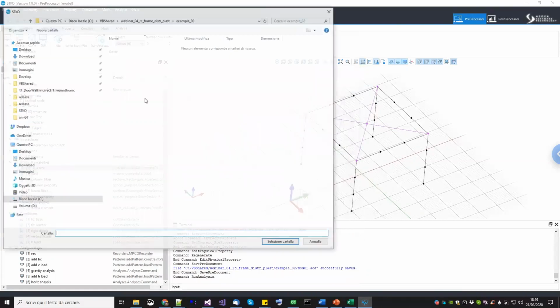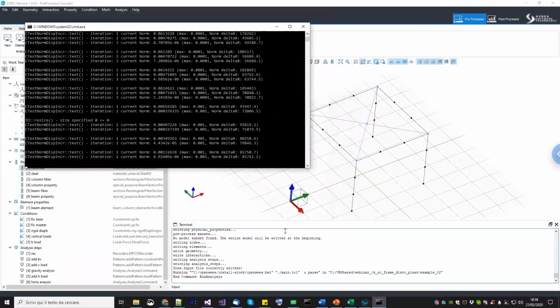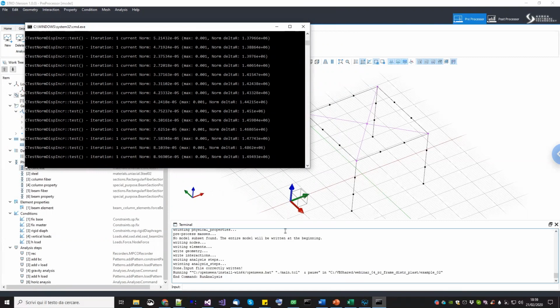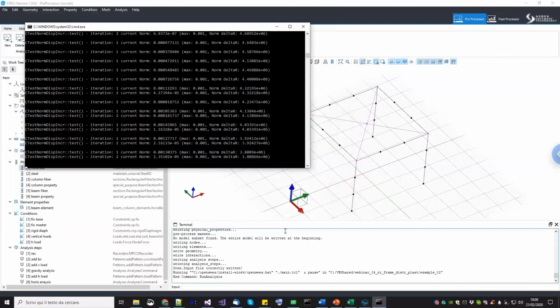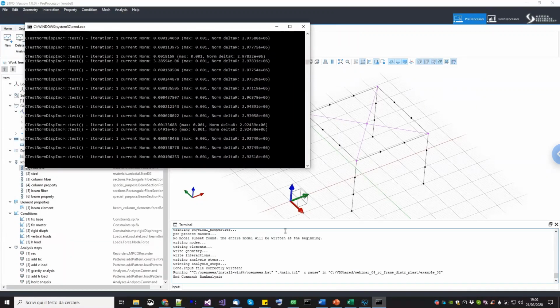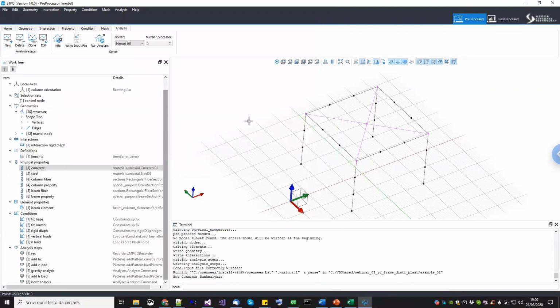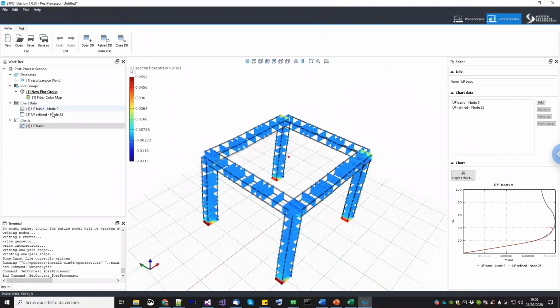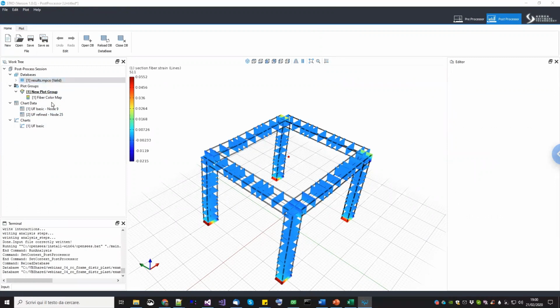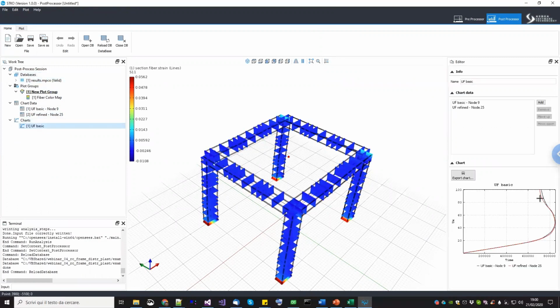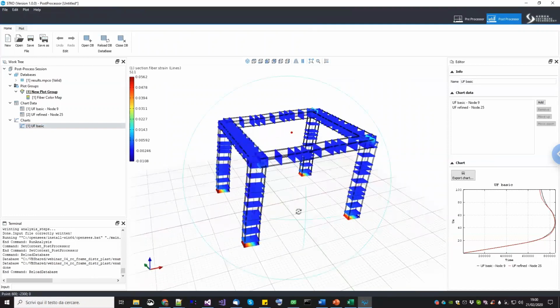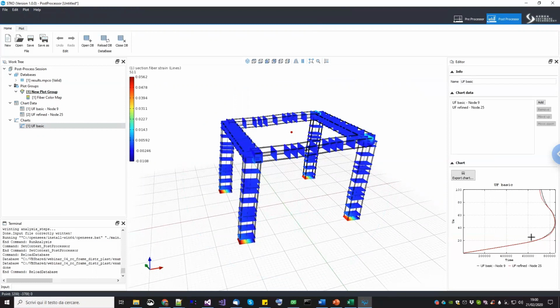And rerun the analysis. And now we should obtain more or less the same results as the original mesh. Let's wait a few seconds. As you can see here, now we converged. We didn't have the same convergence problem as before. So let's go back here. Now as you can see, I left this one linked. So now I go here and I just update or reload the database. Let's go back here. And as you can see now, it updated the previous curve and they are pretty much coinciding. Of course, there is some difference because the regularization is not a very precise formulation, but as you can see, the responses now are basically coincident.